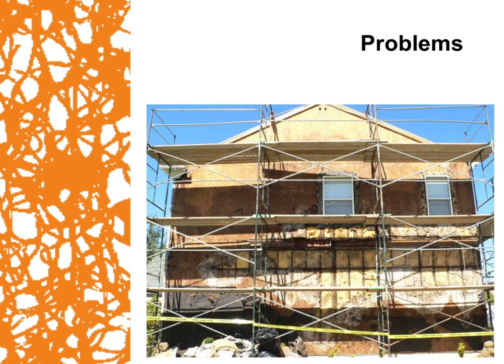These next two pictures are from the same project, in which they again thought they had a small window leak, and as they started to tear away the facade, the area in which they saw the moisture damage kept growing and growing until they had the whole front side of this project torn off. Between the OSB and everything else, it was just getting eaten away. In some points there was no OSB left at all, just like in the second picture, where it's just 2x4s and insulation once they tore off the facade.